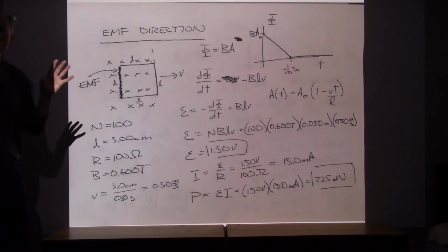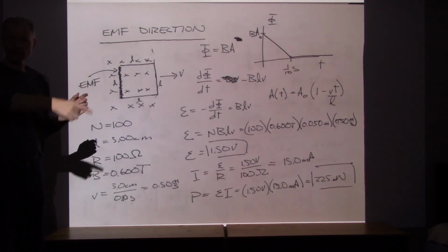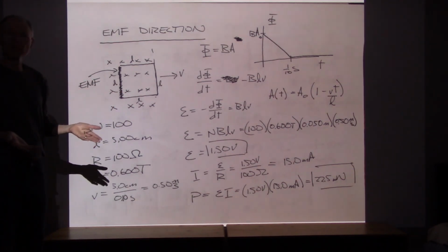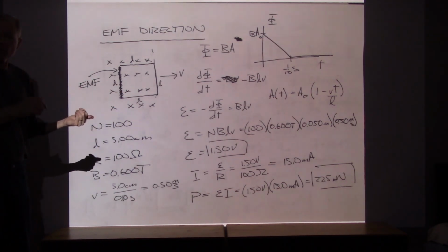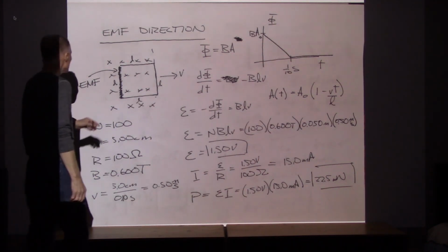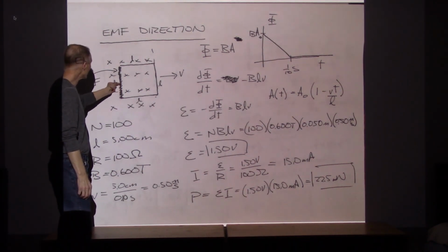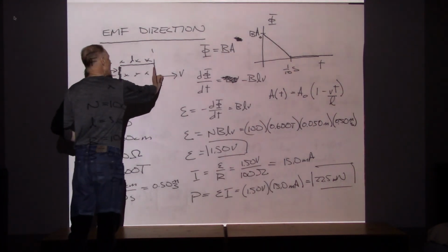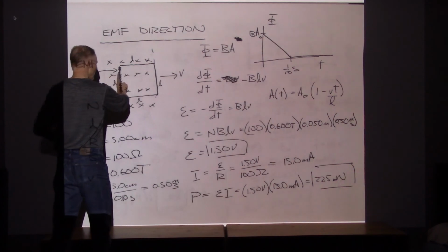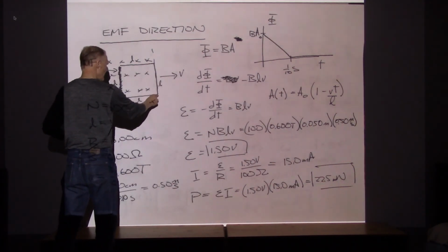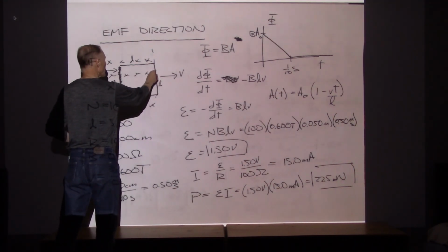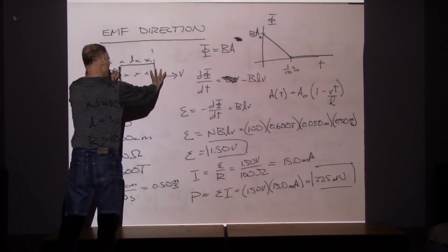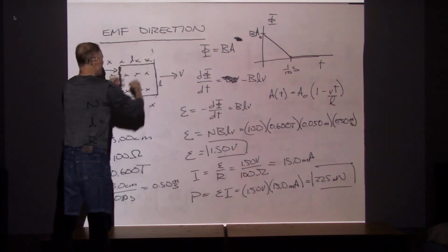Again, Faraday's law just says that in a holistic fashion. Faraday's law doesn't say specifically what's happening at each location. The direct method that we started the chapter out with says that there's an EMF generated all along this length as it moves through the magnetic field. And this length also, as it was moving through the magnetic field, there was an EMF being generated all the way along here. When we calculate these two effects, it's the same amount of EMF, but they're opposing each other.